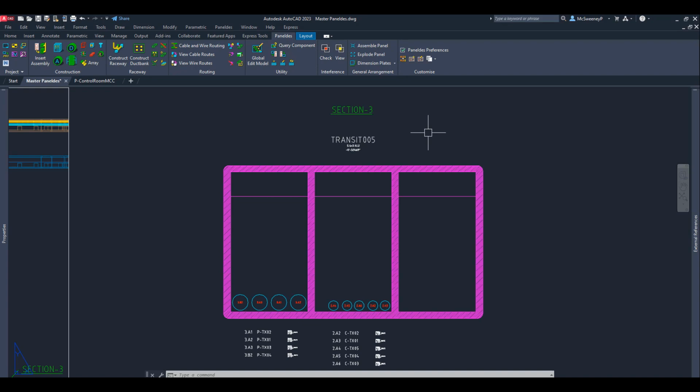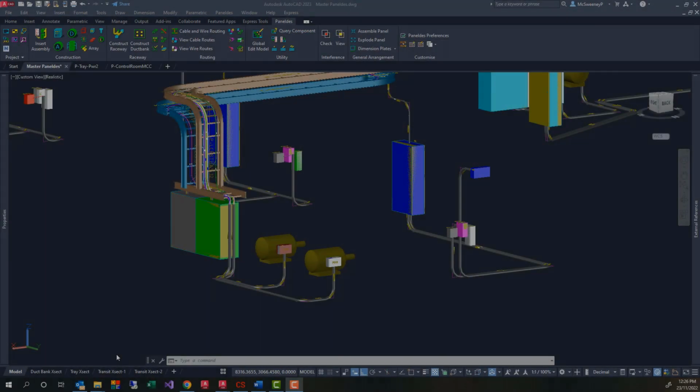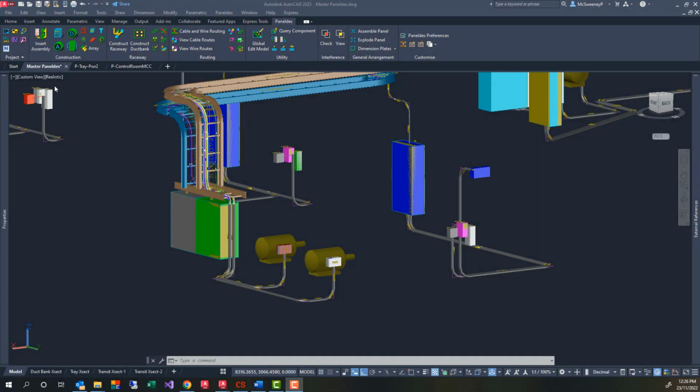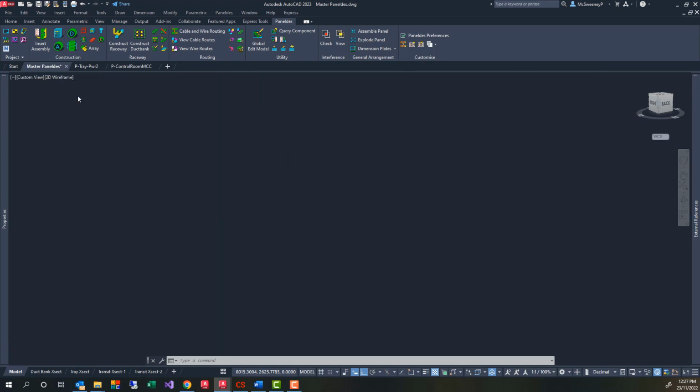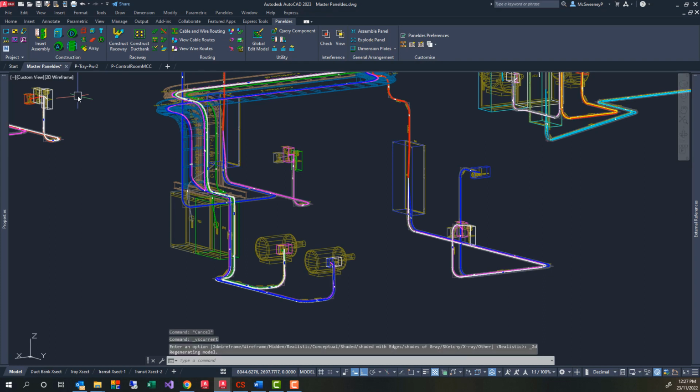The transit system is ideal for offshore room isolation and ship bulkhead designs, with each transit able to selectively allow power to enter a space, or not. Routing and tray design is an iterative process. You can't know how big a tray is until the count of cables in the tray is established. However, routing, not yet done, affects that cable count.